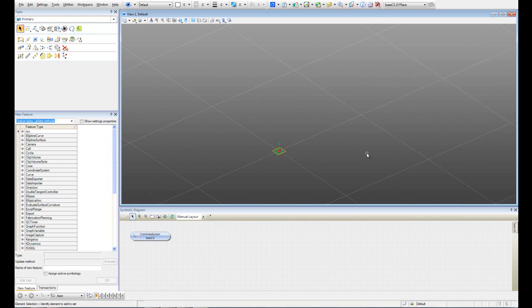Okay, in this tutorial I'm gonna show how to create one component that is gonna be a tetrahedral, and we're also gonna add a lot of features to that tetrahedral. So we're gonna use coordinate systems, we're gonna use planes so we can rotate it. We're also gonna use one feature that is called LawCurve that is really nice, that you can add a lot of variations to your component.